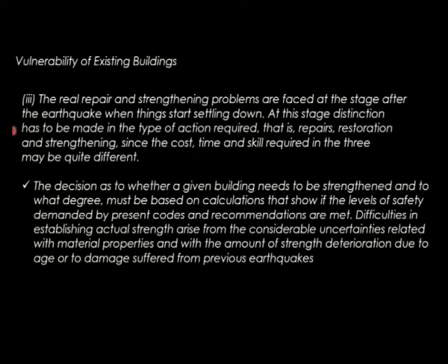The decision as to whether a given building needs to be strengthened, and to what degree, must be based on calculations that show if the levels of safety demanded by preset codes and recommendations are met. Difficulties in establishing actual strength arise from the considerable uncertainties related to material properties and to the amount of strength deterioration due to age or to damage suffered from previous earthquakes.